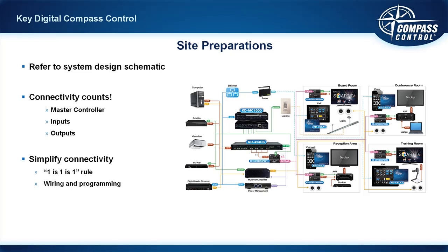So the connectivity counts. Make sure you have a detailed diagram, because not only in the field but also the programmer behind the computer should be following that. Your inputs, your outputs to your multi-zone devices, your master controller, IR1, IR2, RS-232, number 3 of the multifunction ports, etc., etc. What are they connected to?